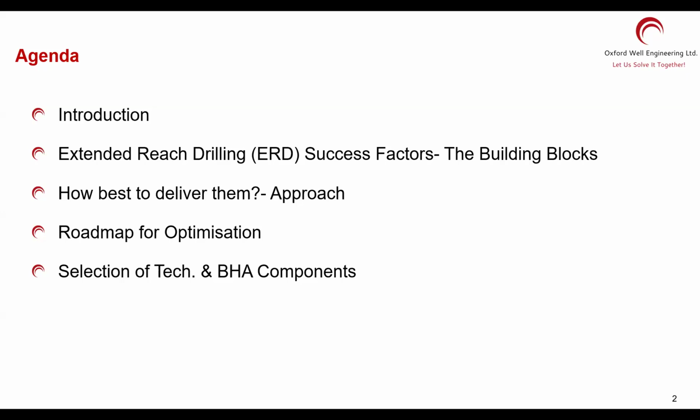And also, we did not touch on one thing, the measurement of parameters. If you're drilling normally, you have certain measurements. If you're drilling for ERD, you may want to enhance the portfolio of that measurement. You want to see the downhole better for the parameters you are after.